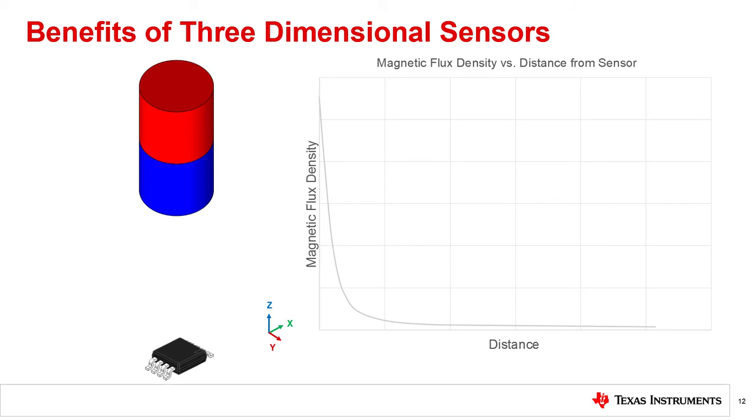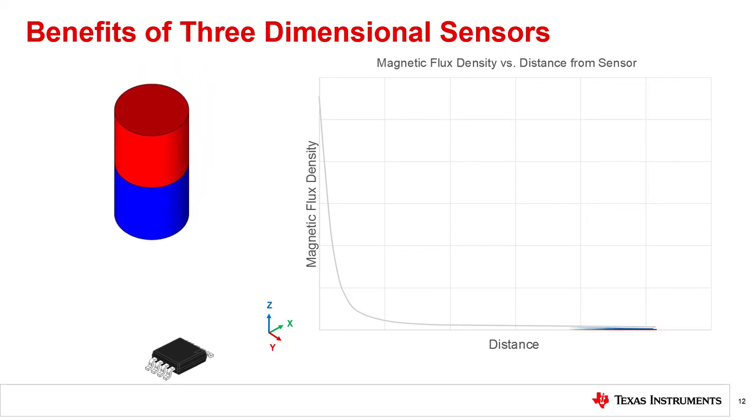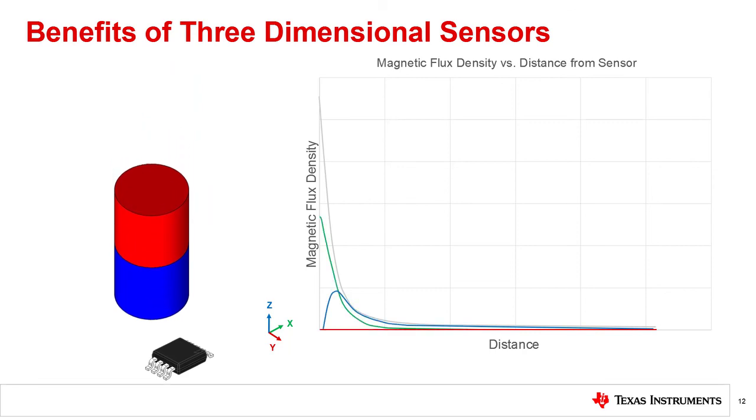Finally, returning to the head-on alignment with offset, we now observe all three field components. Taking each into consideration, we can calculate the magnitude of the field vector and obtain a response which is similar in behavior, although lower in magnitude, to the scenario with the sensor perfectly aligned to the pole of the magnet. In effect, we achieve greater design flexibility while being more forgiving for mechanical tolerances. This enables precision motion detection even in unusual circumstances.